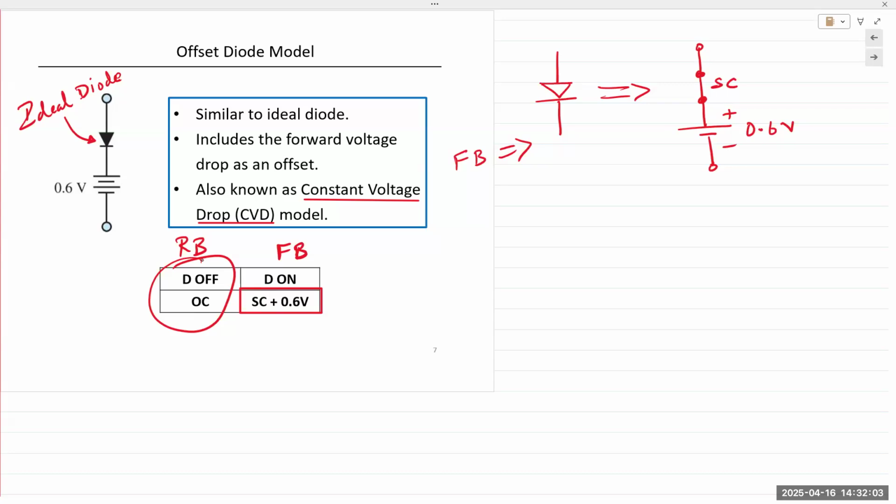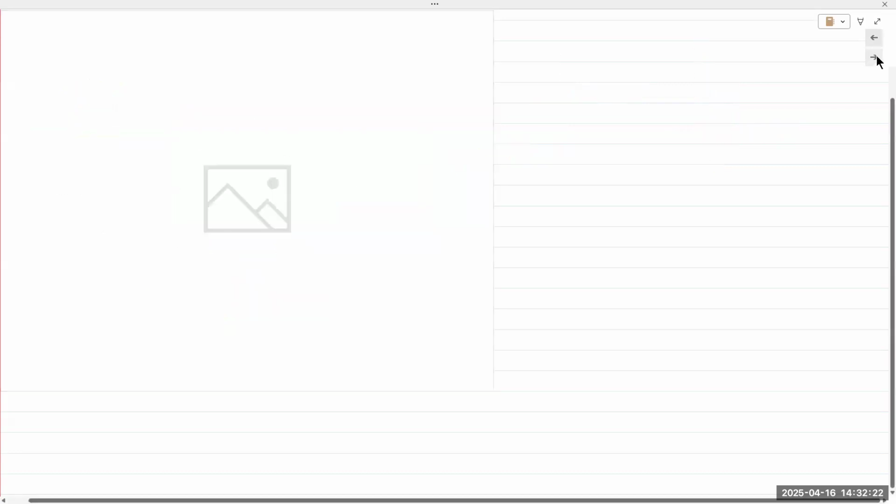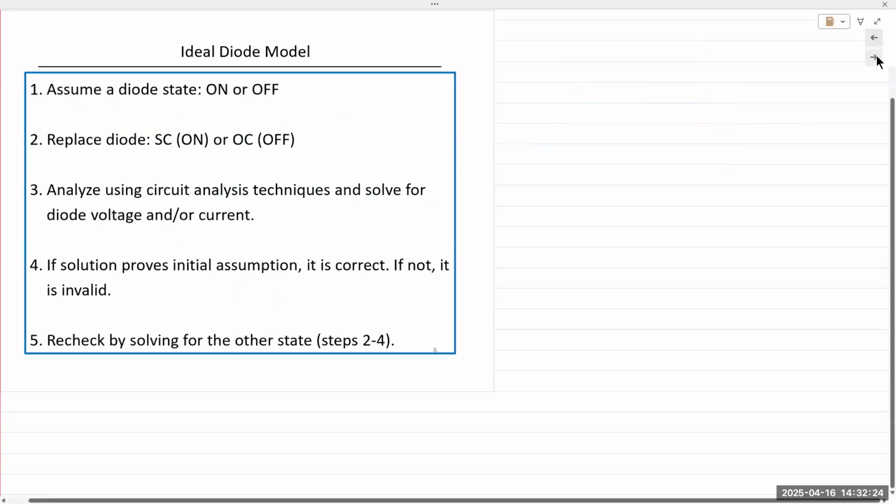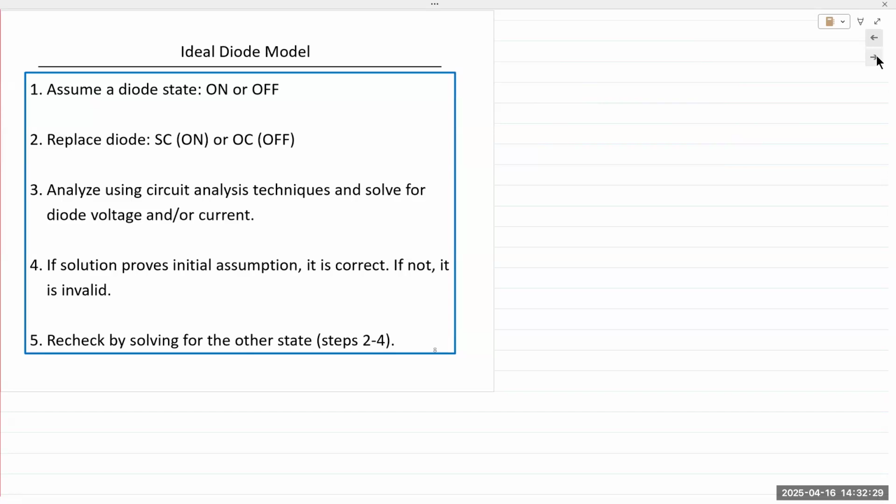You pass gas into a vacuum chamber, typically methane gas that contains carbon, at the right pressure and temperature; it decomposes, carbon separates out, and it deposits onto your sample as a diamond film. That's chemical vapor deposition. So I have to be careful depending on what class I'm teaching, because CVD means something else.